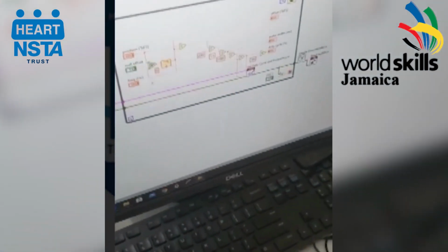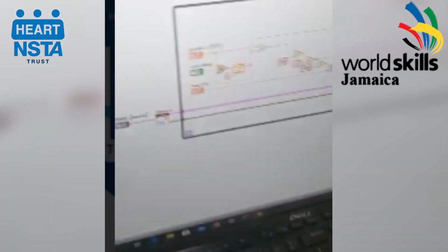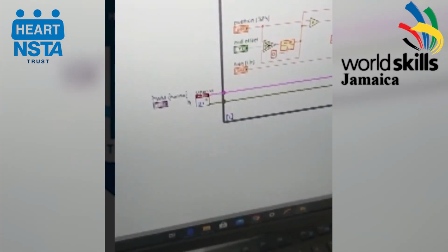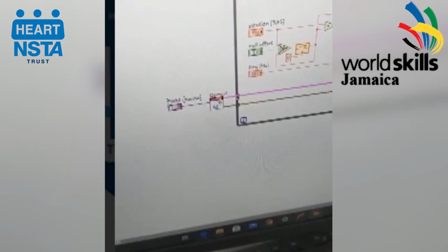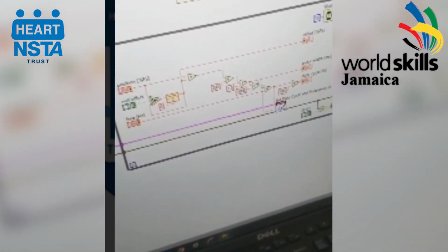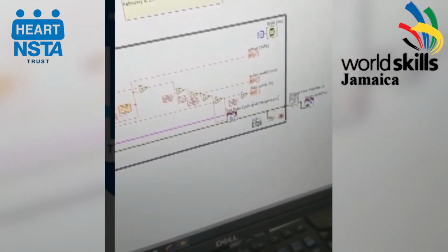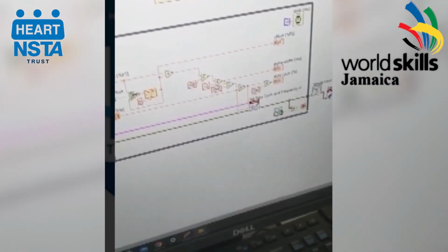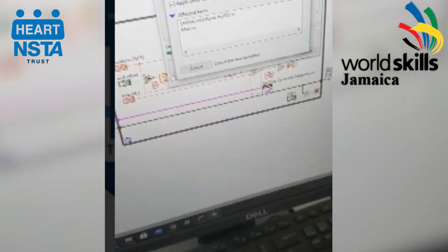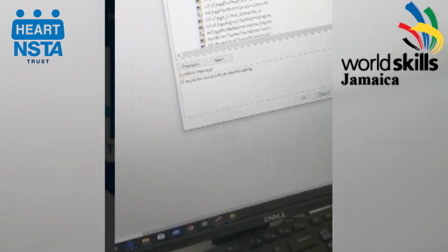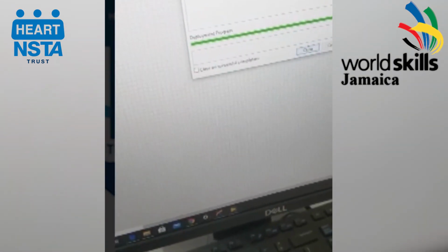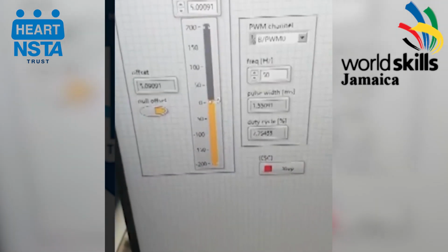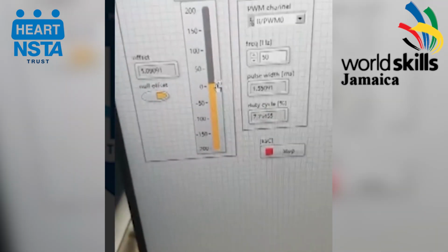This is the application here. We set the PWM channel, pulse width modulation channel, here, and then we perform a mathematical operation, and then we put an output to the servo motor. And if we run this, we see here, this software also gives us the graphical tools necessary to control the servo motor.